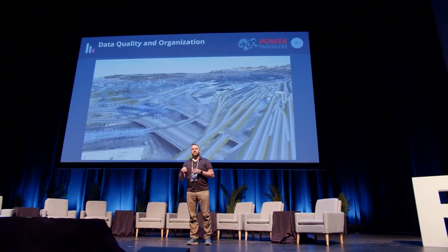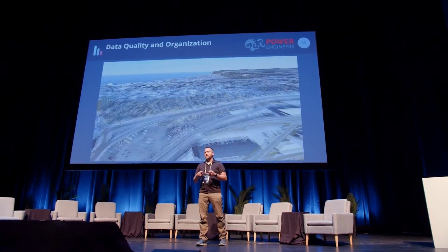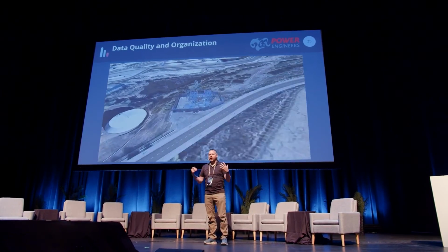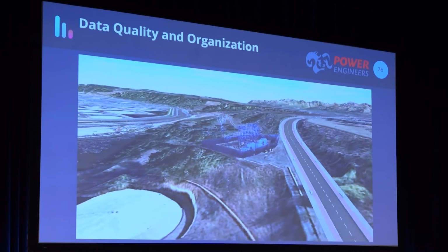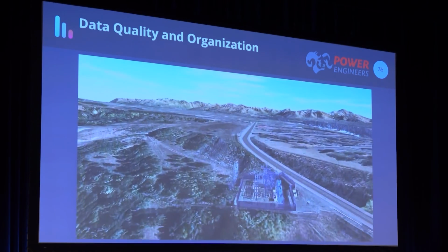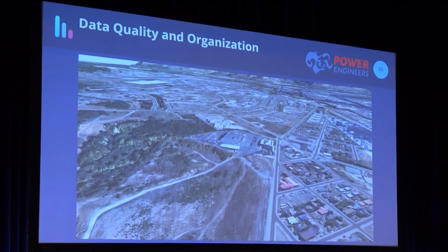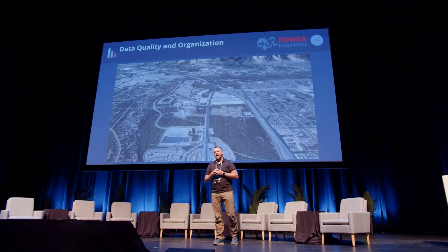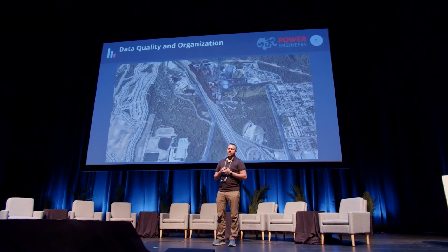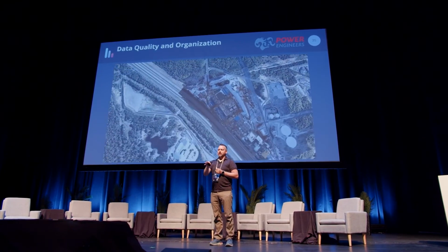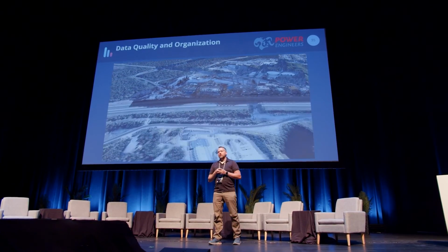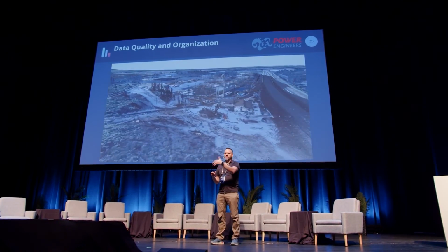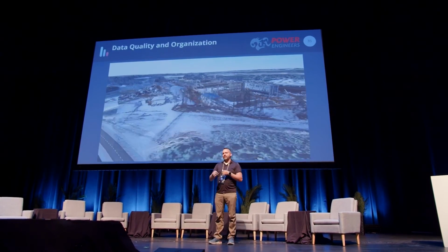So we have requirements for when we capture data: survey control, geolocation, temperature, time of day, point quality, point density, accuracy of those scans. All those components allow us to take this data and steward it through that life cycle so it's usable to the next person. We can aggregate multiple different types of reality capture data into a single data set for visualization. And we can look at different timelines for capture. We can associate that to projects and dates and times and know when it was captured, what it was captured for, and then leverage that for future processes.